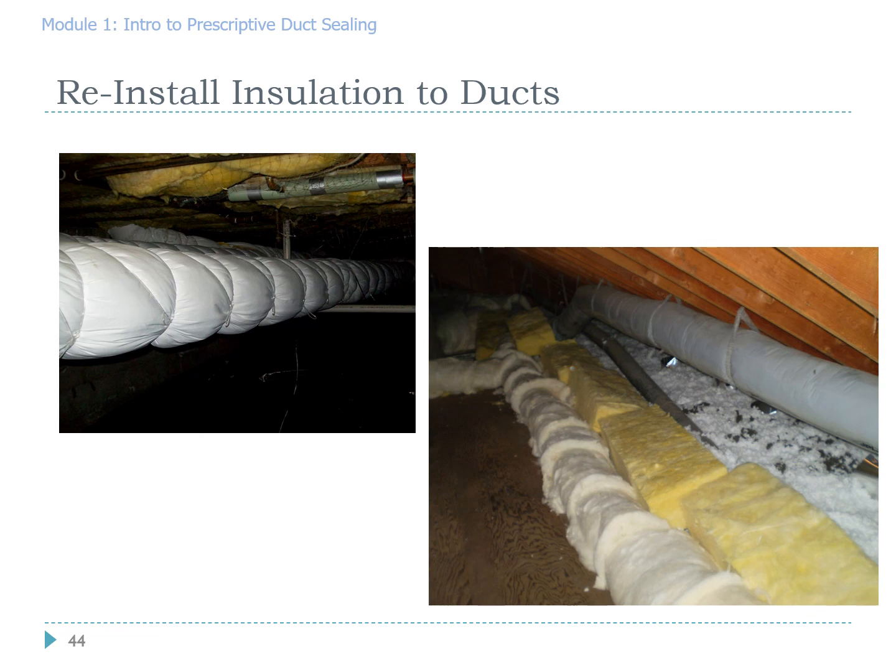If you have removed insulation for duct sealing, it is imperative that you reattach it. It is not your job to reattach insulation that has fallen off before you got there, but if you have removed any insulation, it is your job to reattach that insulation.